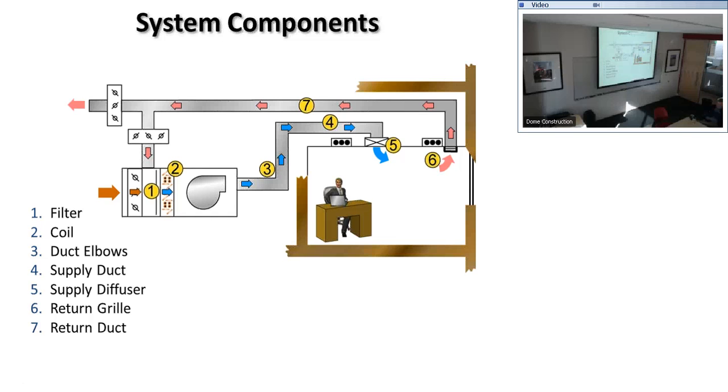Some beams I see you have to fireproof them. So I'm not sure of the issue with the beam. Yeah, it's got to be non-combustible, which is why you got to use plenum-rated cable and stuff like that. It's got to be all non-combustible.